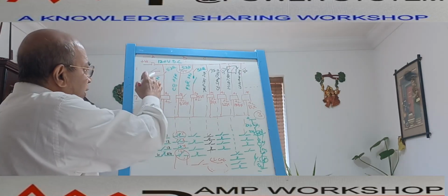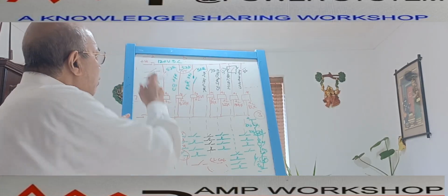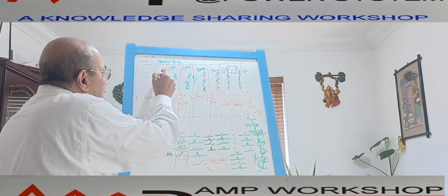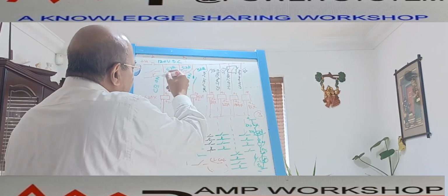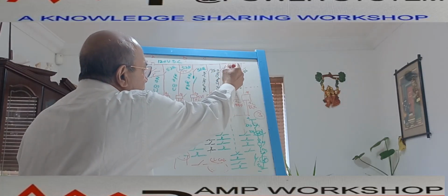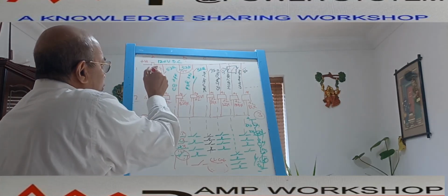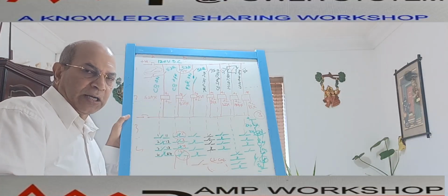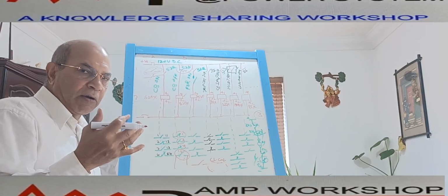So if the MCB trip condition is to be sensed in multiple locations, one contact will not be enough. So what do we do? We use this MCB NO contact to multiply the contacts. We use one of the MCB contacts, and we can connect it over here as MCB trip. As this is a multiple number, suppose this is one of the tripping circuits, similarly the closing circuit, then the alarm indication circuit, all of these have an MCB contact.